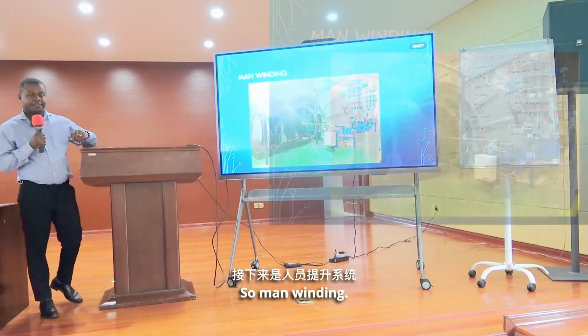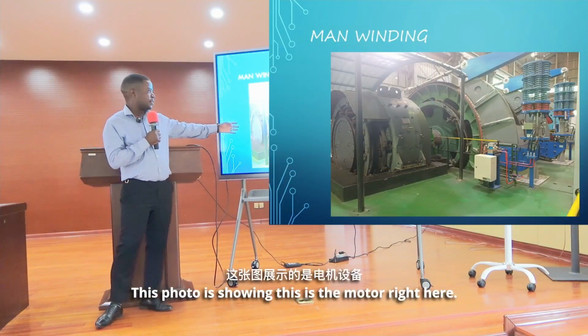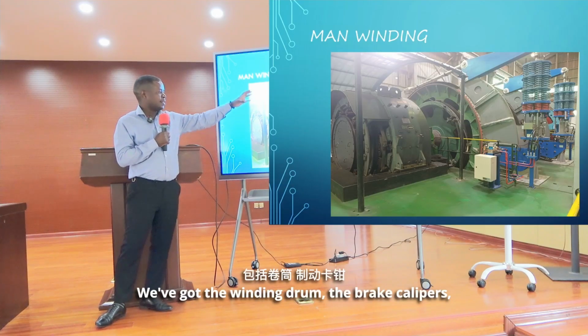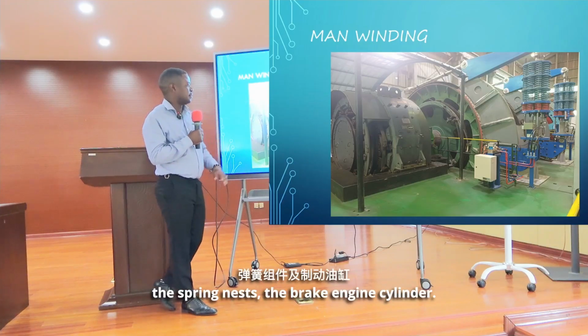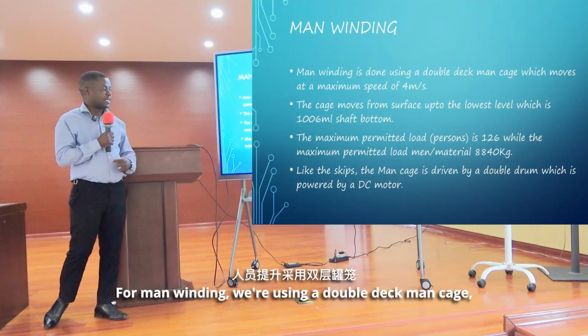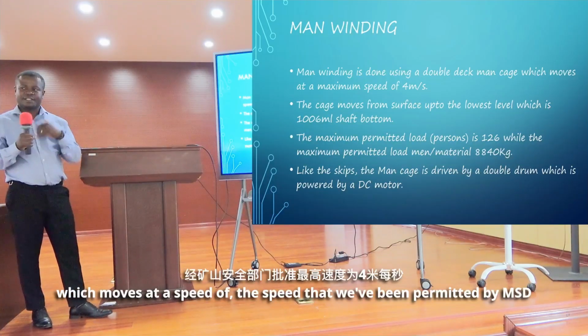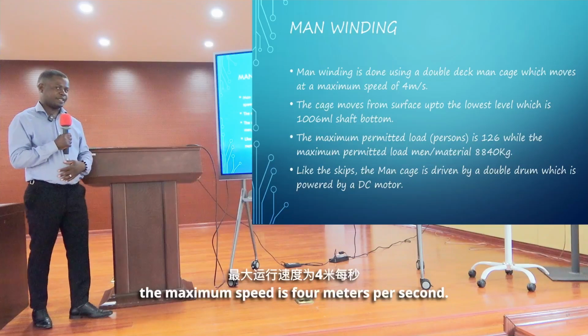Now man winding. This photo is showing the motor right here. We've got the winding drum, the brake calipers, the spring nest, the brake engine cylinder. For man winding, we're using a double deck man cage, which moves at the speed that we've been permitted by MST. The maximum speed is 4 meters per second.